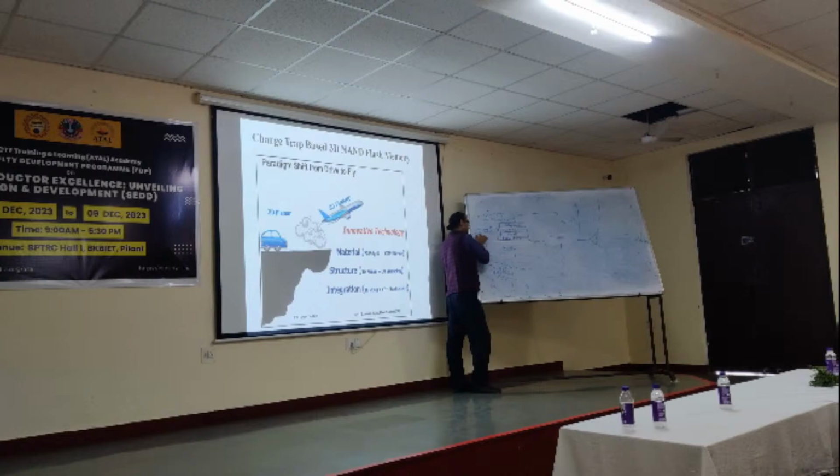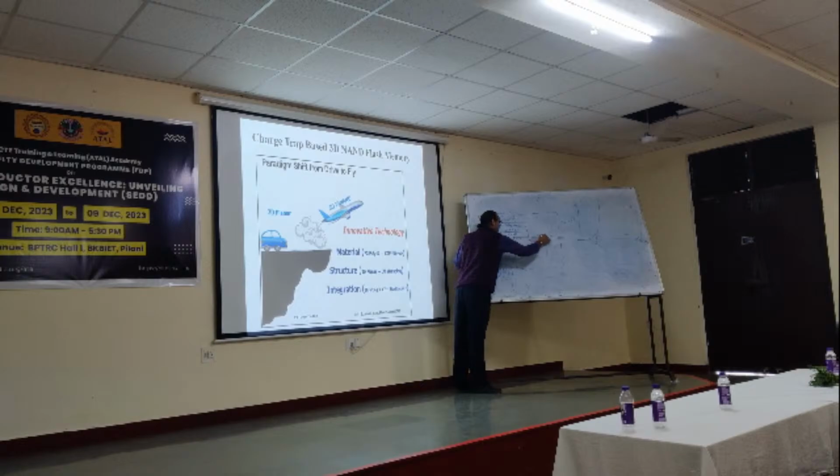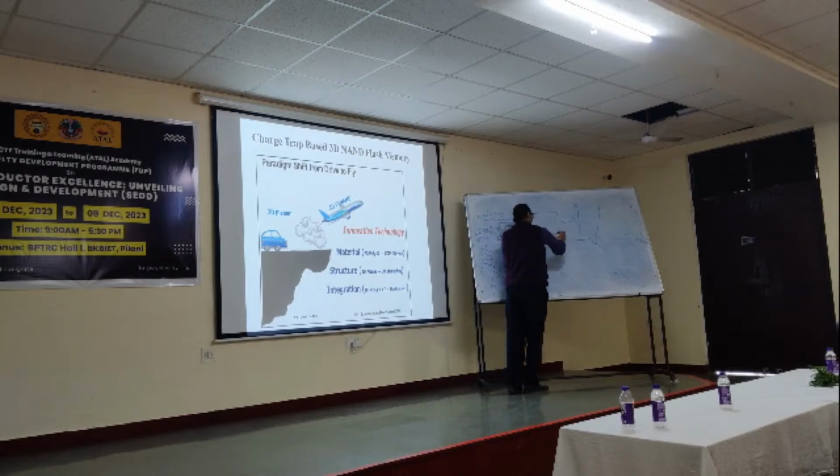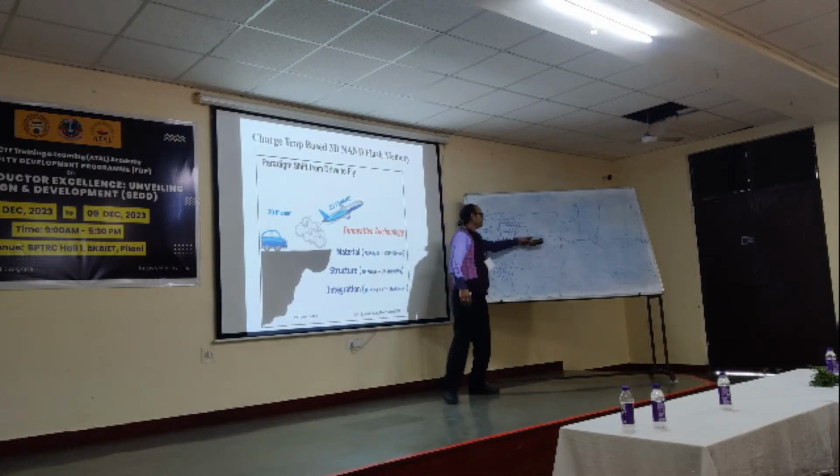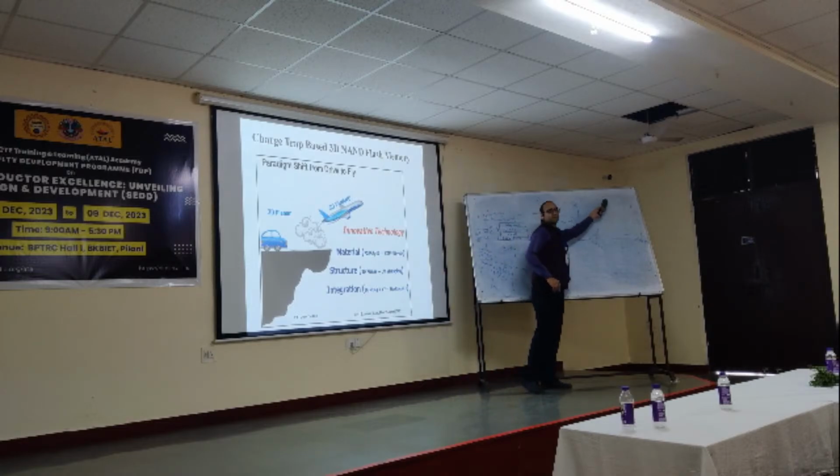And normally we have source, grounded, and we have drain. So say I will apply 1 volt at the drain and fix it, and what will I vary? How do we plot ID-VGS characteristics? Anybody? I will vary gate voltage, no? Keeping drain voltage fixed. Now, suppose I will get this kind of characteristics. This was a fresh device.